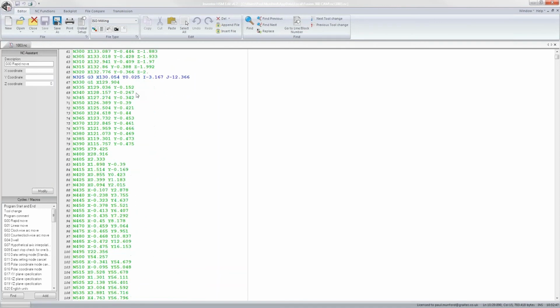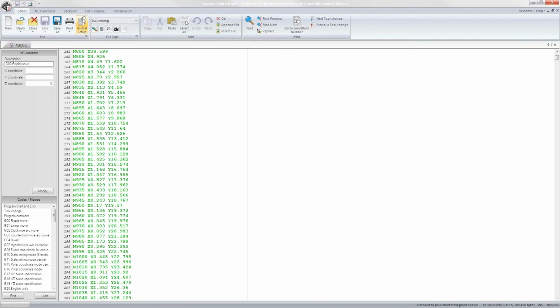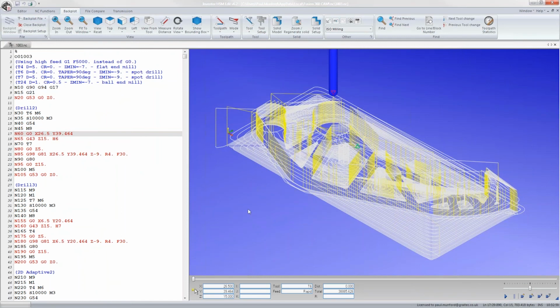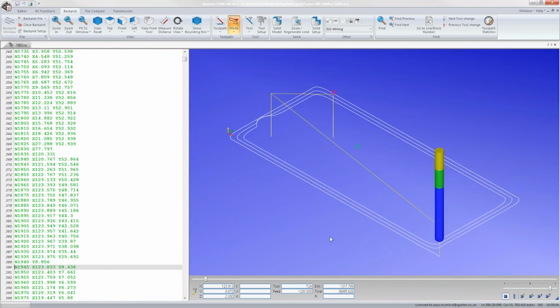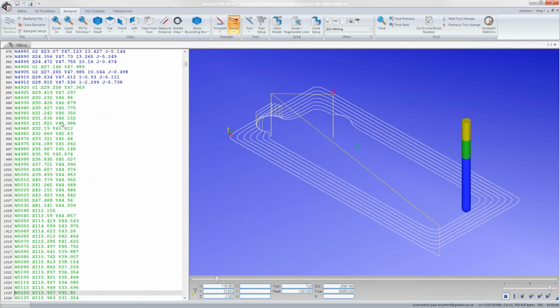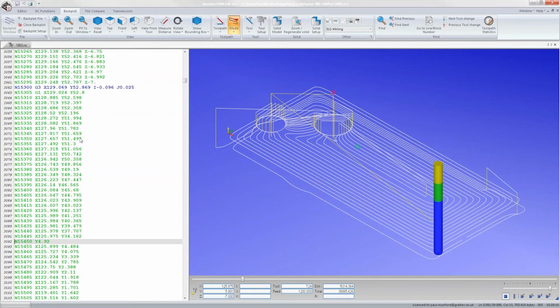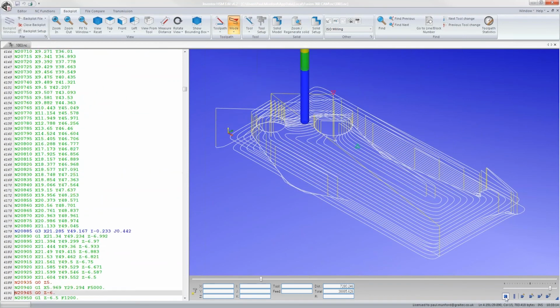So this is where we can see the G code. So we could go through here line by line if we make any tweaks, tweak our speeds and feeds, we can do it straight from the code. But we also have this backplotting option in here, so we can take the code that's being run and we can do a simulation actually on the post processor as well. So we should see a pretty similar result through this post processor, but now we're seeing the G code run, and again we can do any further tweaking just to make sure that's as completely optimized as it can be through this post processor window. So that all comes with Fusion 360, which is again a pretty awesome deal.